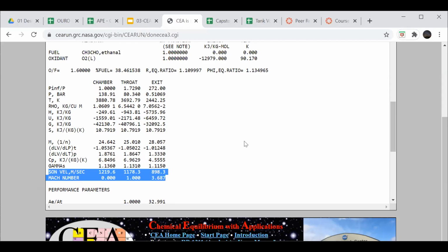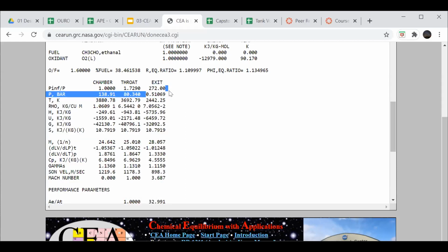Okay. And then Joshua, why would you not want exit pressure to be equal to atmospheric? That's exactly it. This one is designed for a higher altitude than atmospheric. For anything that's fired statically on the ground, the most efficient engine you would get is if this exit pressure is 1 bar, and whatever the pressure ratio corresponds with that. This one is just going to be maximum efficiency at whatever altitude 8 psi is. I think they spec that for 20,000 feet.